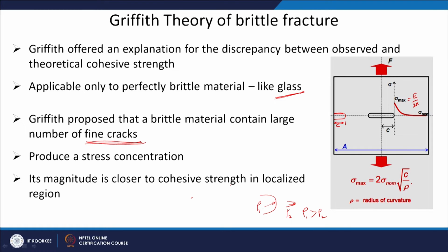So, when my rho or crack is getting sharper and sharper, this value will be smaller and smaller. Because it is in the denominator, the sigma max value will be even higher. So, a bigger crack and a sharper crack make the sigma max even higher. You will have a higher local stress, and it will be easier to fracture the material. So, overall stress is much lower than the local stress. So, this is what we discussed.